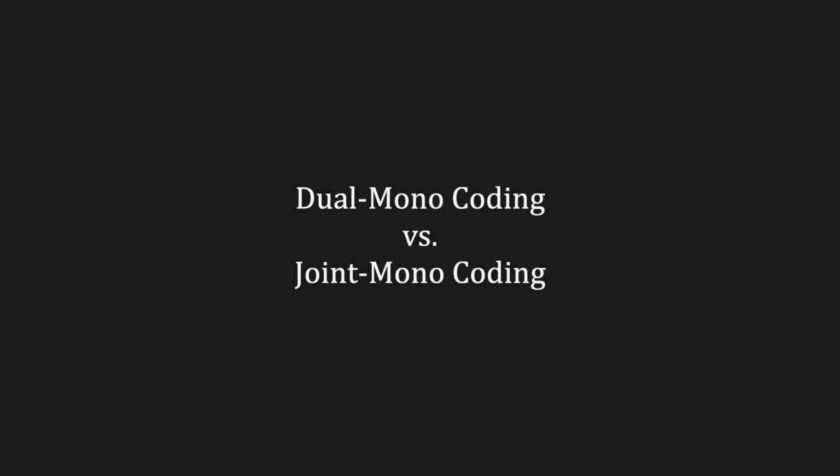If stereo channels are coded poorly, one may interfere with the other, breaking the stereo image. Dual mono coding treats each channel separately, while joint mono coding shares a total bit rate between them. Independent channel coding can cause audible noise if spatial masking isn't aligned properly. Multichannel coding must handle the delicate psychoacoustics of how both ears perceive sound. Joint stereo coding improves efficiency by using shared information between channels. Since stereo usually shares level and phase data to create a spatial image, it's more efficient to code this common information once instead of twice.